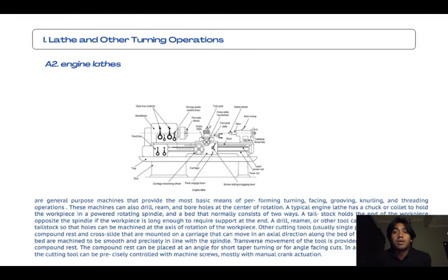The compound rest can be placed at an angle for short taper turning or for angle facing cuts. In all cases, the movement of the cutting tool can be precisely controlled with machine screws, mostly with manual crank actuation.